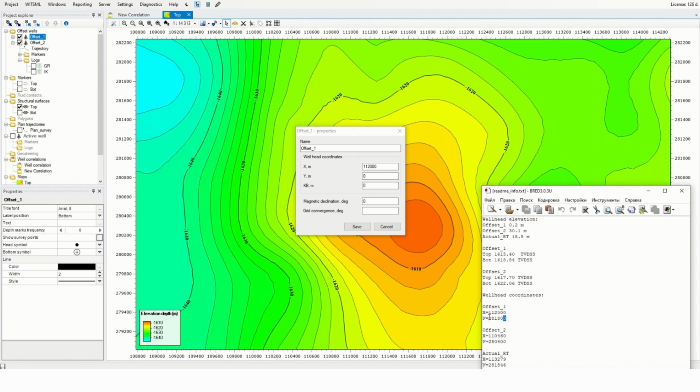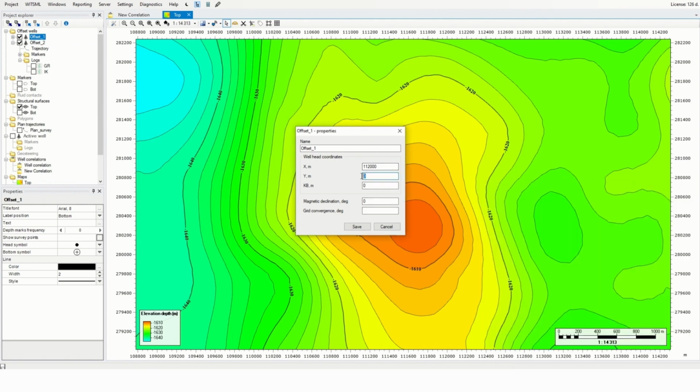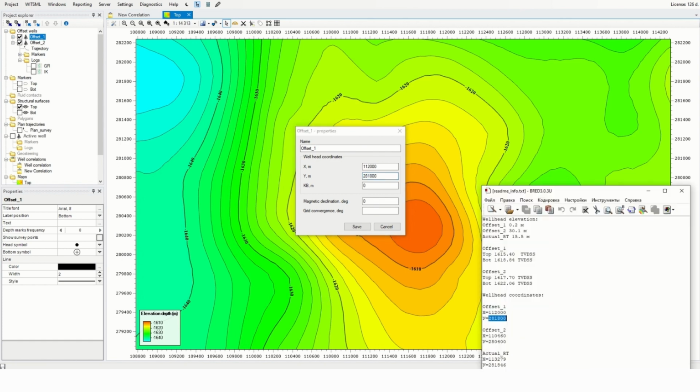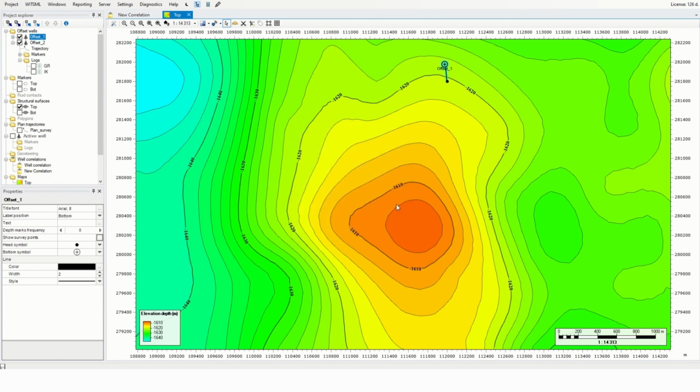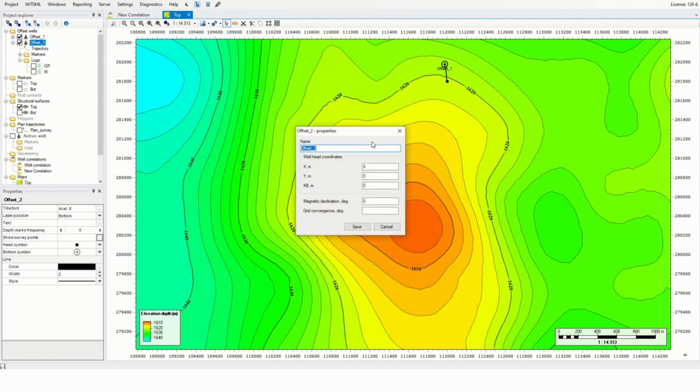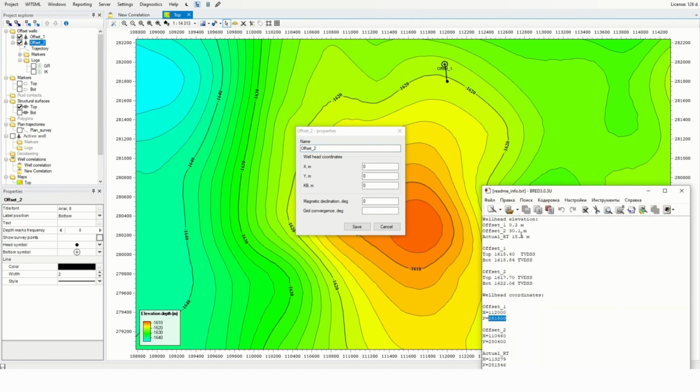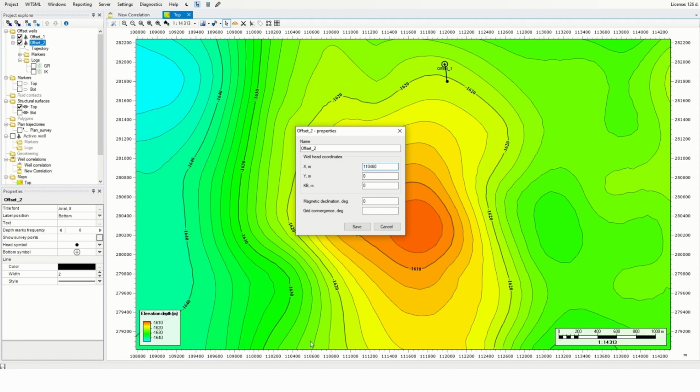Okay. Let's do the same for the second well. So actually, you can avoid this extra step if you had a different template for the trajectory. As you see, we imported the trajectory first and then manually we put coordinates. But normally from software like Petrel, you can export in a well format, so the file contains already the trajectory and the wellhead coordinates. So you just drag and drop it here and that would be much easier. But for this project, we had this file. So let's follow these steps. Okay. So now you see the second well is there.